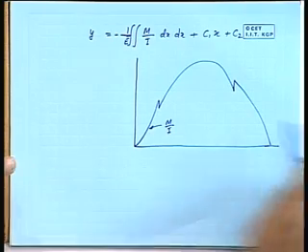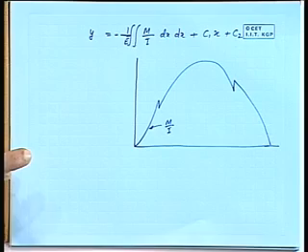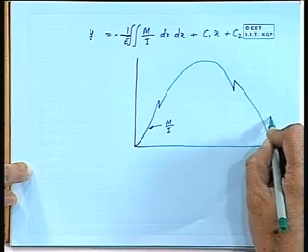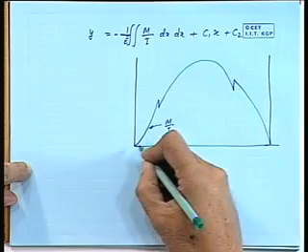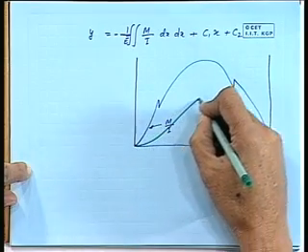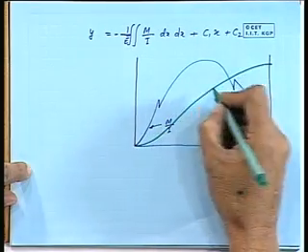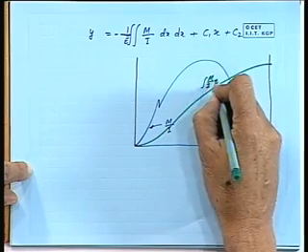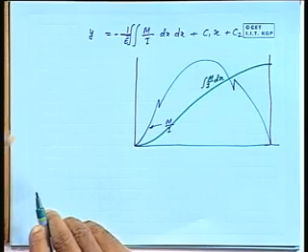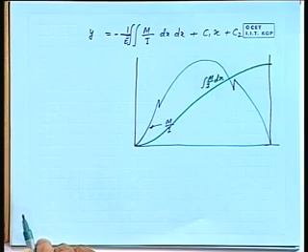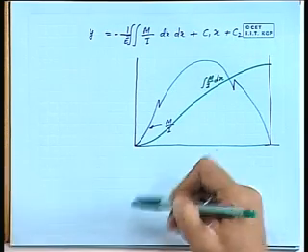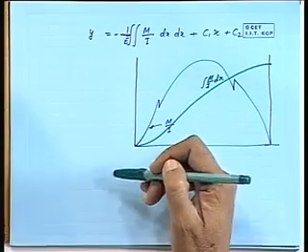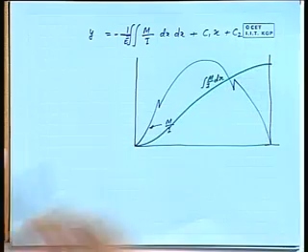So, once we have the M by I curve, we can now try to integrate, and once we try our integration scheme, we find that this is the first one, which is M by I dx. Okay. Now, this integration we do in a numerical fashion. That means you find out up to certain areas and keep on adding it, and this curve you will get.